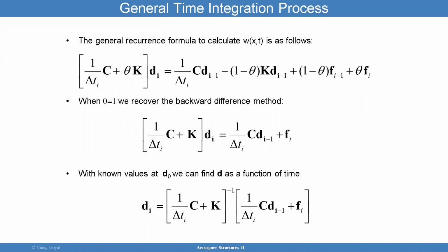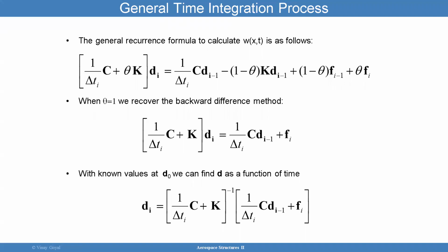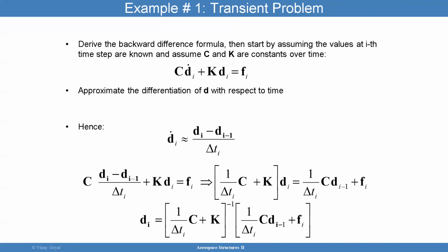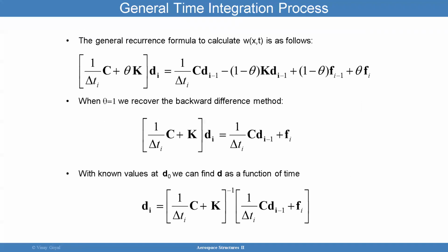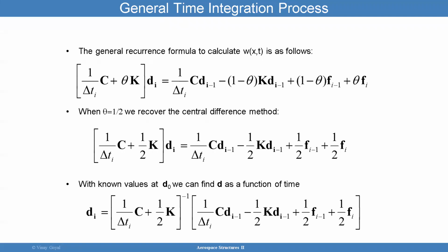And I don't want to bog down this particular lecture, because this lecture again is not about the theory of finite elements, although I'm covering some aspects very top level so that you know how that works. So there are various methods. The method I showed you is called the backward difference method. There's a forward difference method. And so this equation here allows you to look at various formulas like that. So this is your forward difference method in this case. And then here, and I'm moving quickly, you can pause the video and look at it later.